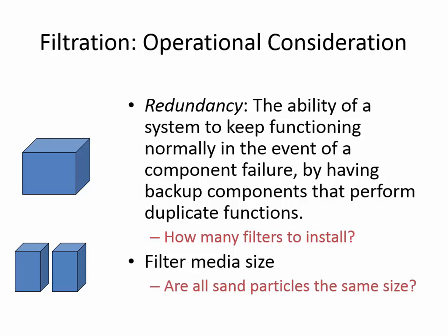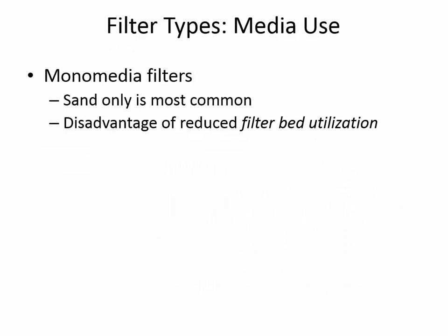And another thing when you're designing these, the operational consideration is the filter media size. If you're only using sand, then you may not be able to remove as many particles as if you use some sand, some crushed gravel, and some crushed coal, like anthracite coal. And a monomedia filter is one that only has one media. That's what monomedia means. And there are plenty of places where they're only using sand.